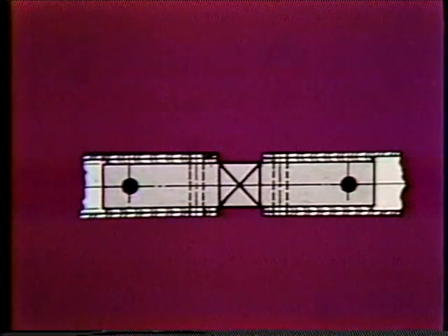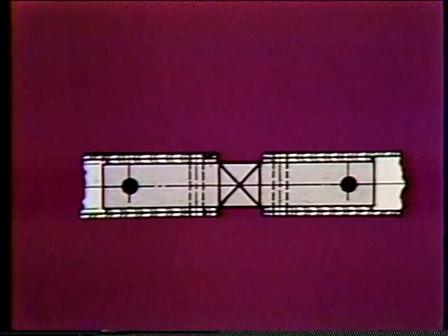Since screw conveyor is normally manufactured in 10-foot or 12-foot lengths, it must be coupled together. The coupling is normally either a short section of larger tubing that will slip over the outside of the shaft and is pinned together with a bolt, or this style, which uses a rod which is inserted into the shaft ends and then bolted into place.